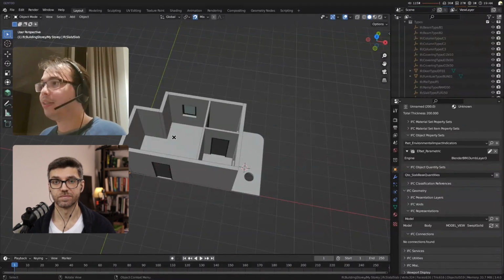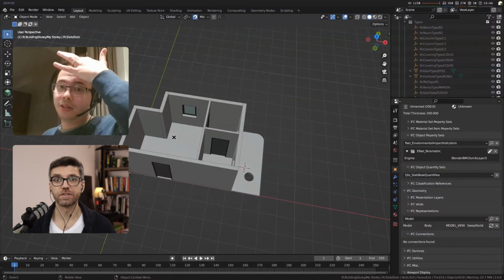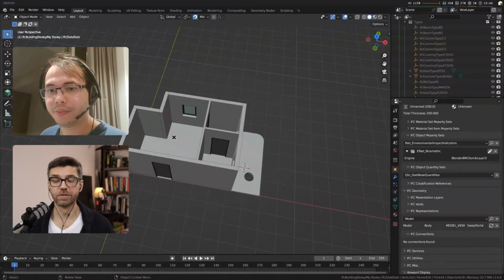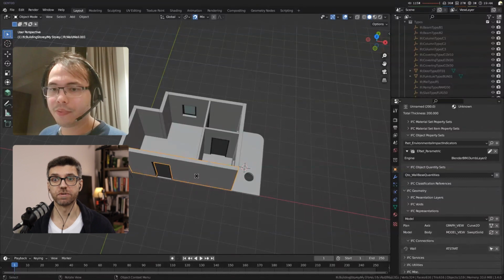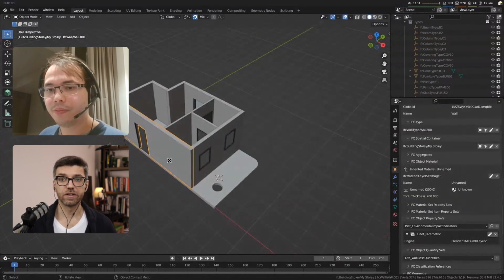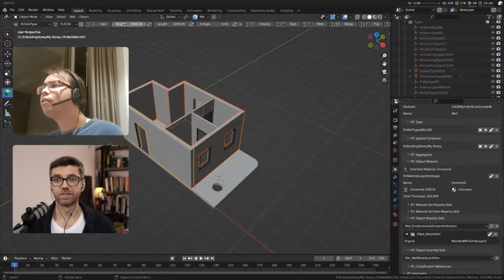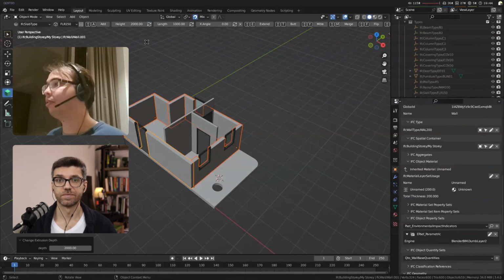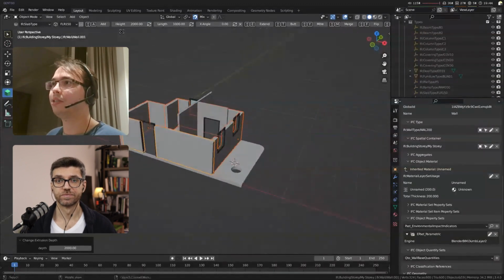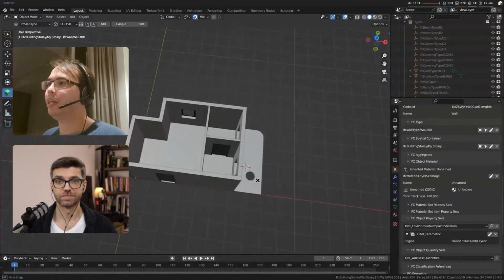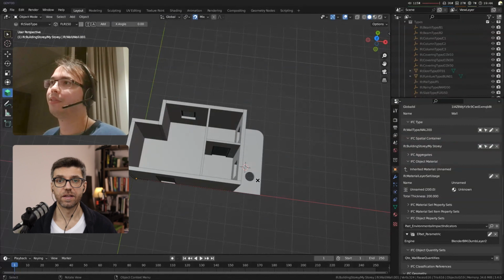Can the height be governed by a level? So let's say you have a level that you mark at plus 3 meters, and could all the walls then go up to that level? Currently there's no parametric constraint that does that. So you'd have to do it manually. You'd select all the walls, click here, select the height, and set it to be, I don't know, 2 meters high. Voila. I didn't select the internal wall, so there we go.